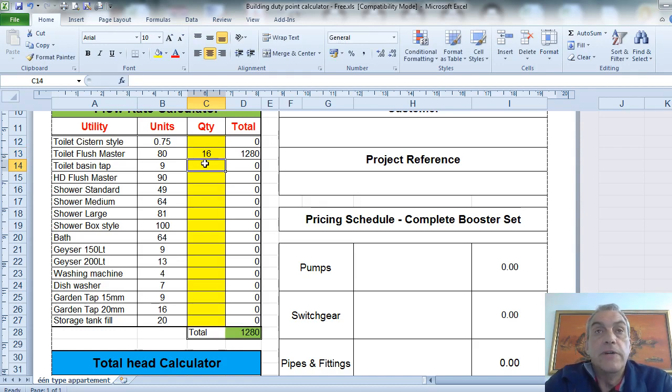Just take into consideration that normally people would use either the cold or the hot water if it's two separate taps, or if you're in a mixer style, which is normally the case in a new office complex, it would be a combination of both. So the calculation that's done here on these basin taps is actually as if it is a mixer. In other words, it's using both hot and cold water. So the unit that we use for that is 9,